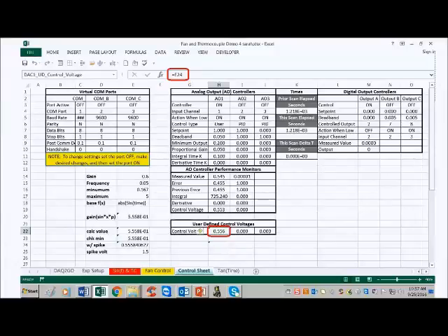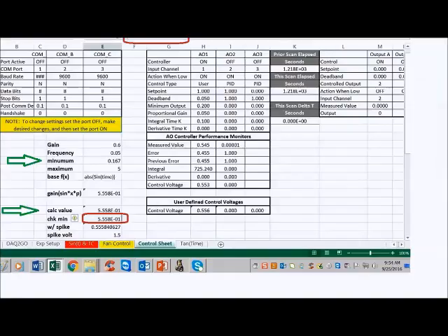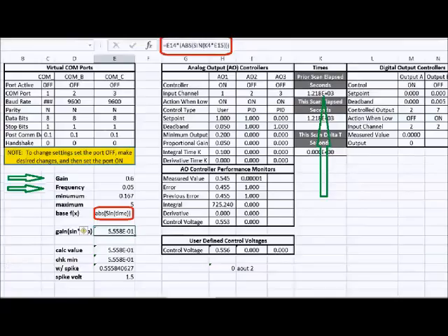The output values for user-defined control are taken from cell E24. This shows that if the time from start is less than 500 milliseconds, the output spike voltage is given to the fan. Otherwise, the calculated value is checked versus the minimum voltage value, and the larger of the two values is sent to the fan. Cell E20 sets the range of output voltage and sets the periodicity of the function.